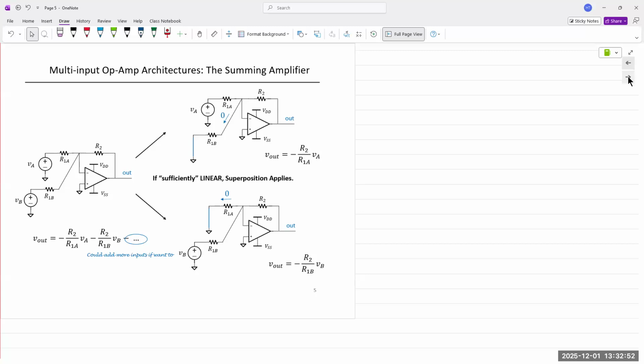Yes, no, kind of. And for a difference amplifier, you have two terminals, positive and negative, non-inverting and inverting. The output of the op amp is basically the difference between the non-inverting and the inverting input, so it's the non-inverting input minus the inverting input times the closed loop gain of that op amp.